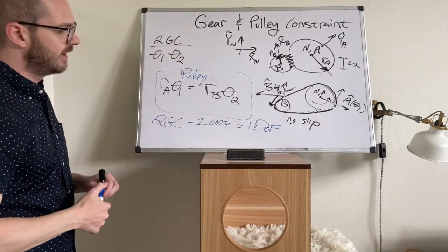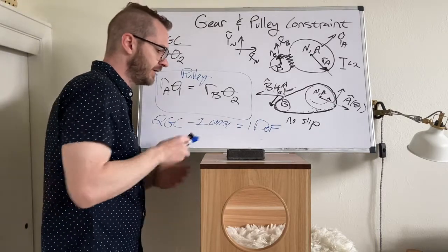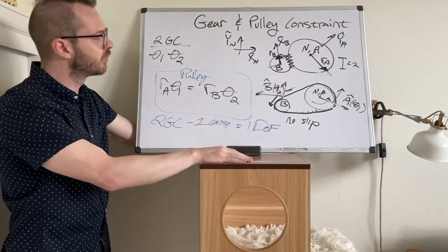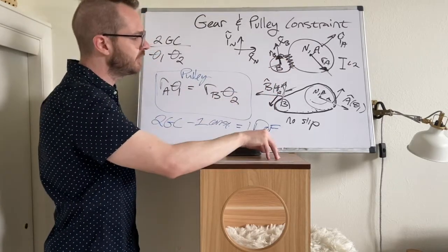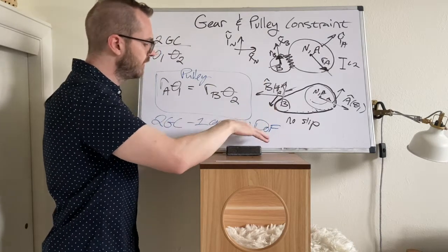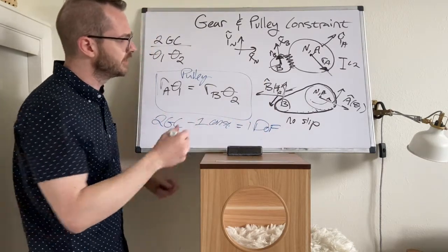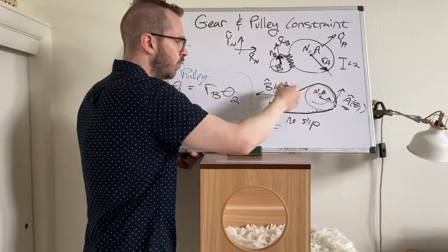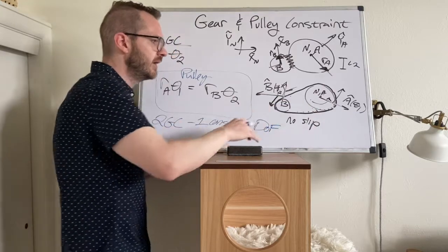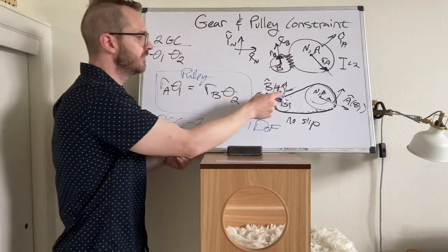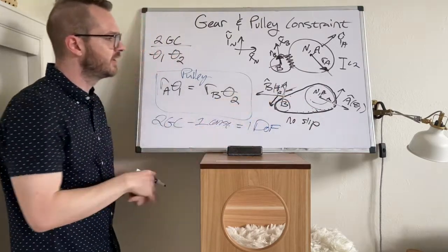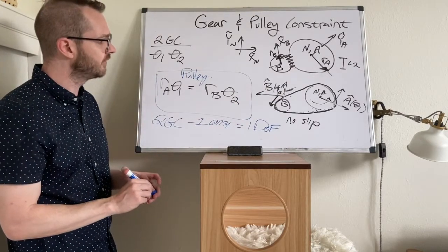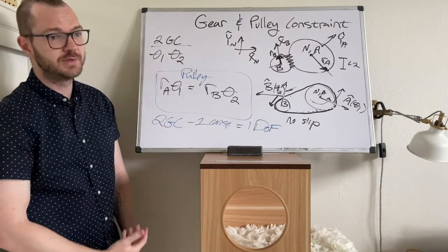All right, so that's it for the dynamics for these problems. You're going to study these more in depth. You're going to learn all about how to design these teeth. You're going to learn all about selecting belts. Some interesting things with belts, there's usually tension in one side of it, and then the other side tends to have a little bit of slack in it, so the majority of the force is on one side of the disc. You will learn all about this, and you will have to consider this when you go to design those parts. But for now, this is what you need to know.